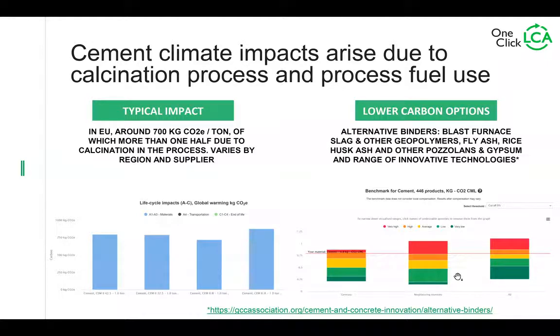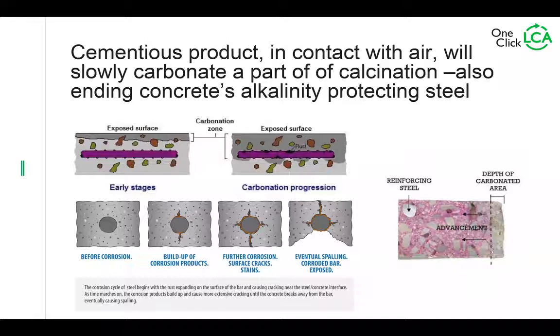And the longer curing time is no problem as long as you design for it. But if you have to get your building erected in, let's say, 6 months, and it's not being designed for allowing longer curing time for certain elements, you could have a little bit of a problem, because your building will collapse if you start to load it before the structures are hard enough, for example. So that's one aspect, right? So we have the cement and how it's developing strength.